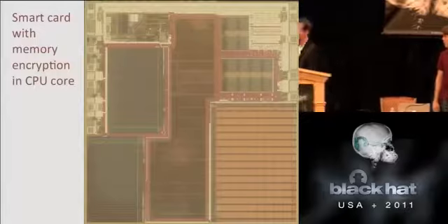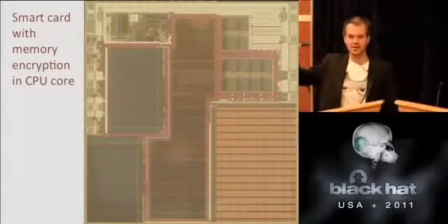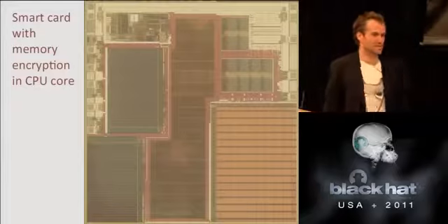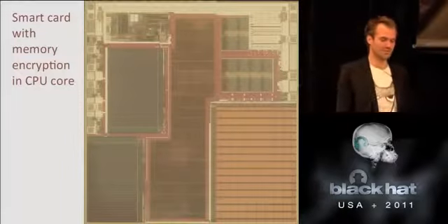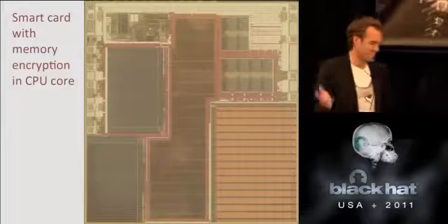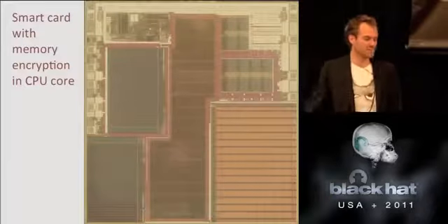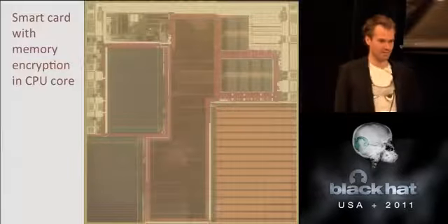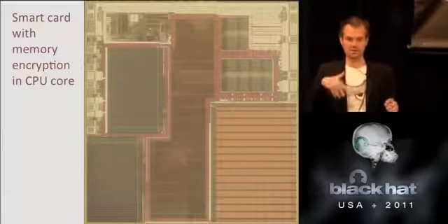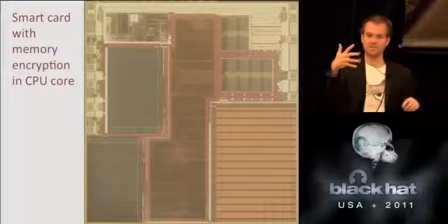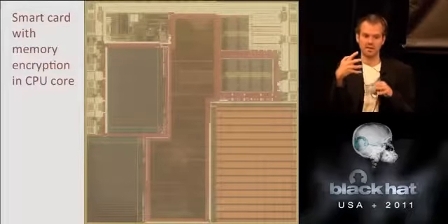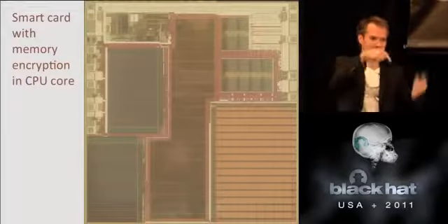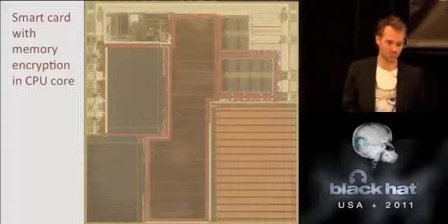Of course, if you just started taking images of everything and then had everything reverse engineered, you'd get a lot more information than you wanted to begin with, since really you're looking for the memory encryption function, and that'll be off this. How many gates are there? Maybe 100,000. Maybe 2,000 are spent on memory encryption, if even that. So if you could tell people to go about it a little smarter, see where the ROM lines come in, and then start with the gates really directly connected to that, and take the gates just after that, and the gates just after that, probably save a lot of time.